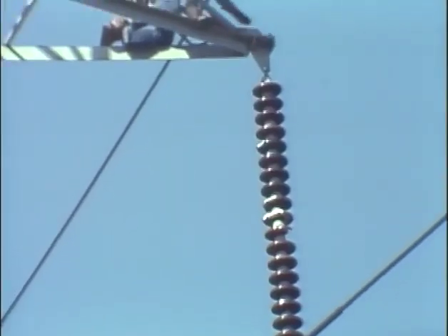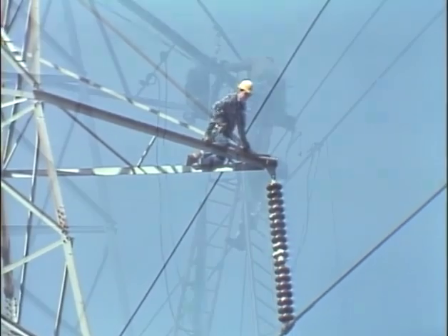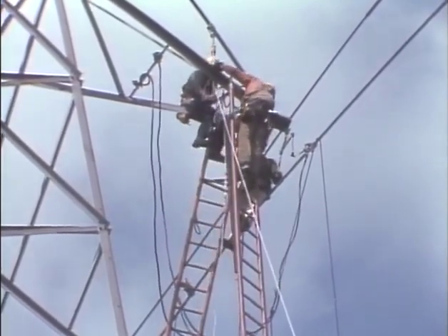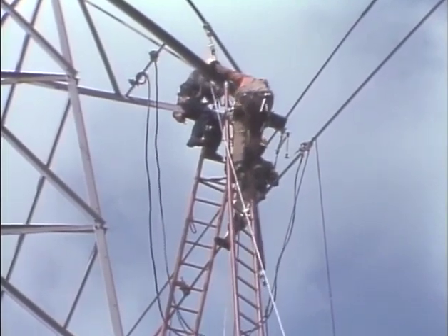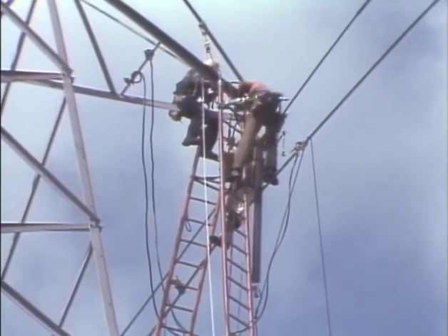The only factor a lineman can affect to change the capacitance of a transmission line is spacing. For example, let's say you had to replace a damaged insulator or stack on a transmission line. If you used a different insulator from the one in the plans, you could change the design configuration of the line by decreasing or increasing spacing. This would cause capacitance to increase or decrease from design specifications. Once again, separate incidents like this may not critically alter the overall amount of power loss in the system, but if they are repeated down the line, they could cause a cumulative change in transmission power.